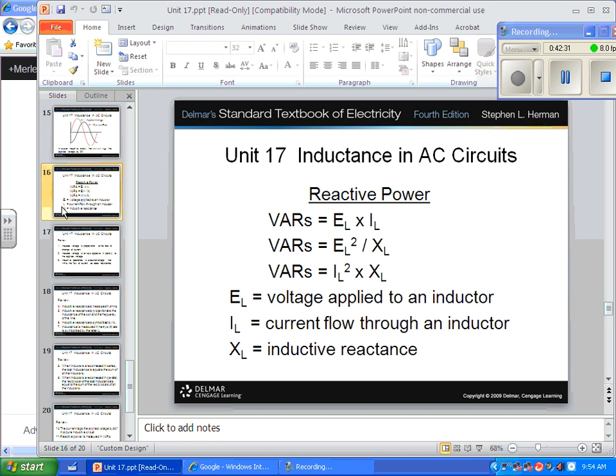Okay? I want to tell you one other thing before I talk about AC or motors for a second. When we start up a big motor, we talk in motor control about how there's a big current inrush when you first plug in the motor, right? You know why that is? Because the magnetic field in those windings has not built up yet. So there's no counter EMF. So the only thing restricting the flow of current through that winding is the pure DC resistance, which is much lower than the total impedance.